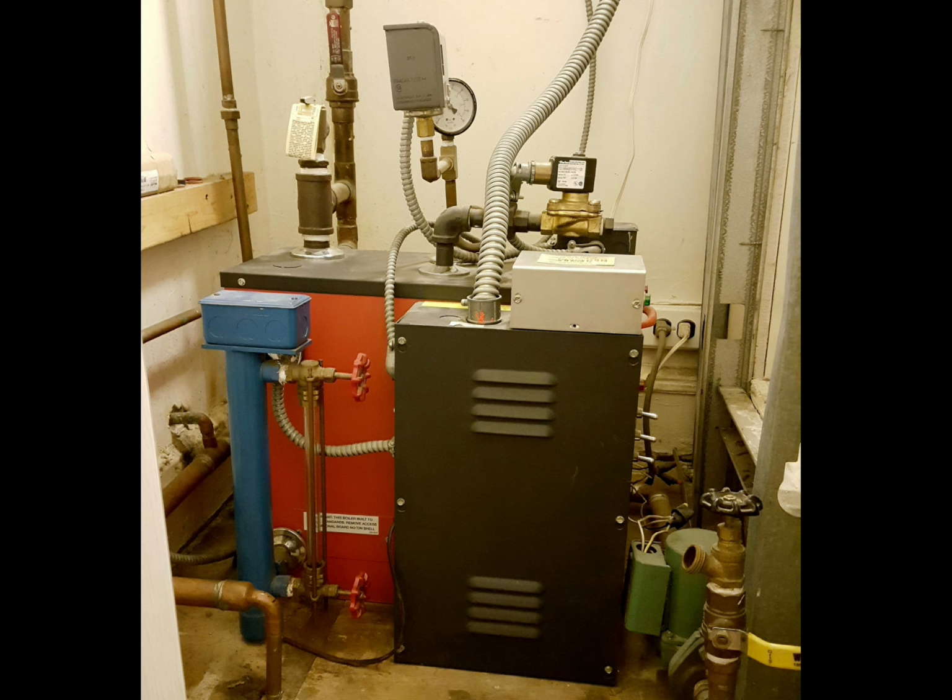When I looked it up initially back in 2005 before I purchased it, I looked at the specs, and according to the specs, these things are designed for heating up bathhouses and sauna rooms. 740 cubic feet is what this thing was capable of heating up. So I said, clearly, if this thing can do 740 cubic feet of steam, then I should be able to heat up 5 radiators in a 3-bedroom apartment with no problem. So I had this boiler since 2005, and it ran 11 winters straight on me.